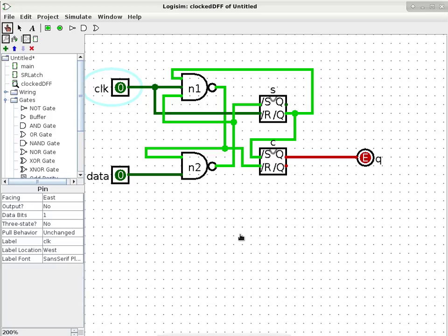But what is important is we look at what happens when the clock goes from 0 to 1. What do you think is going to be the biggest change? It's going to have an immediate impact on two things. So which two things does it have an immediate impact on? If you just track down that node. Okay, so we track down this node and go like, oh, N1 is going to change. The output of N1 is going to change from a 1 to a 0 because once clock goes from 0 to 1, right at that moment, N1, after a very short amount of time, is going to output a 0. And where is that 0 going to? That 0 is going to two places.